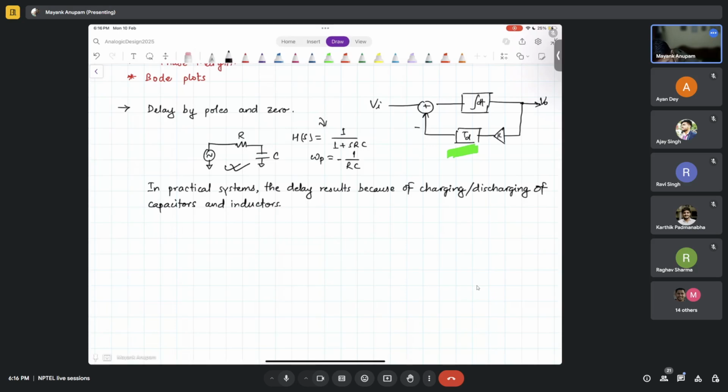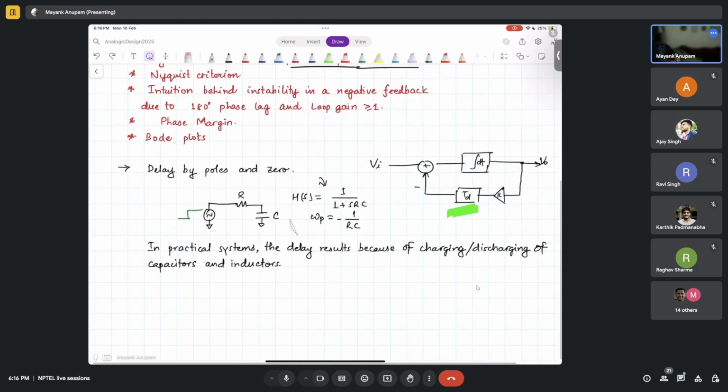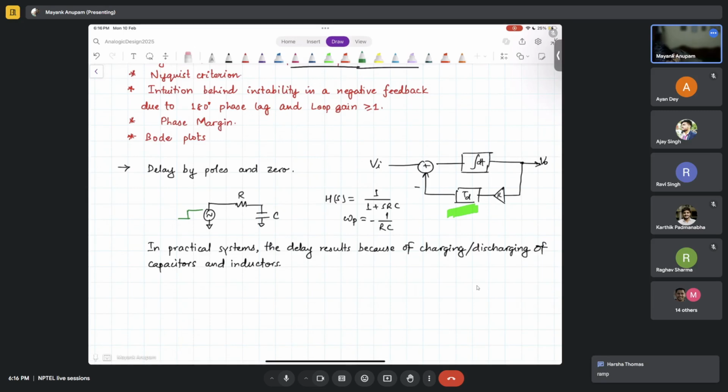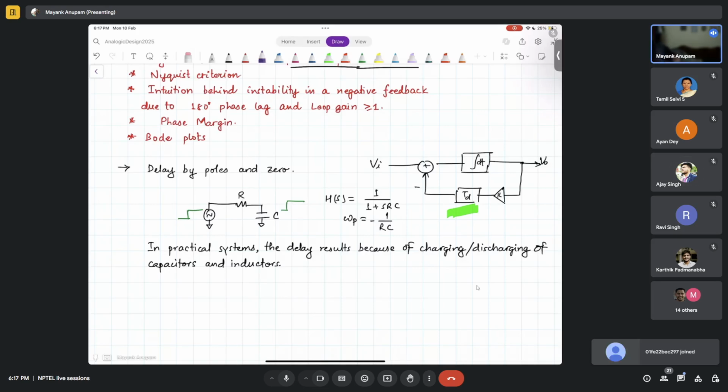And what is the unit step response? If someone asks you what is the unit step response, how will it look at the output? Slowly it will be charging. First, an exponential, yes, exactly. So, exponential increase in response to the input, which goes like this, the output will be slowly rising, right? It will slowly rise.